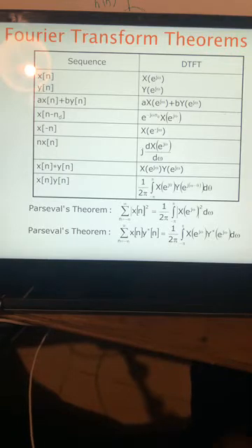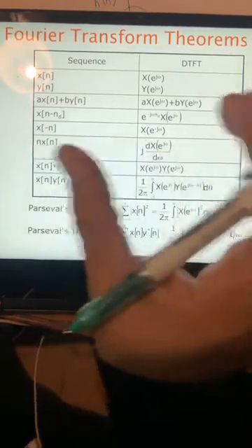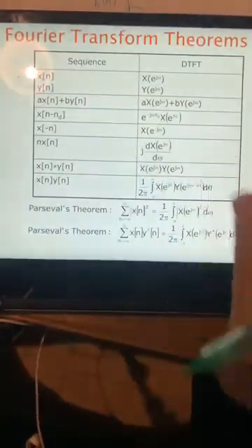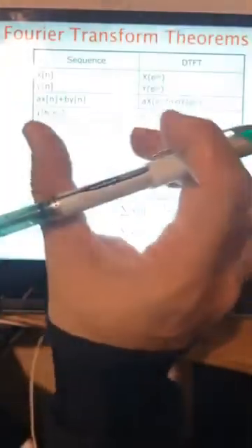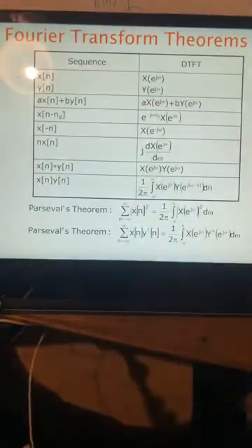Yes, you only require current and previous input samples, and that's why you shift the impulse response. Instead of it running from -m to m, it runs from 0 to 2m. So you shift and make it causal.